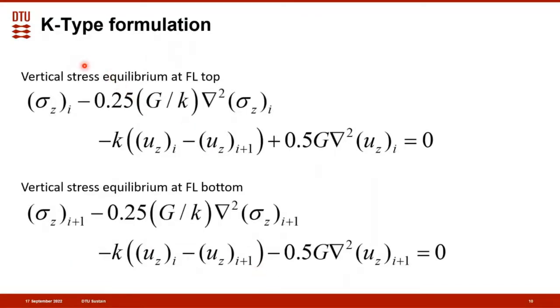The vertical stress equilibrium at the top and bottom of the fragmented layer is different for the K-type formulation, but the other requirements are the same. So in case of a K-type formulation, these two expressions should replace the previous two.